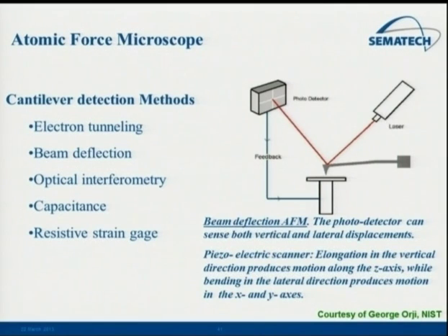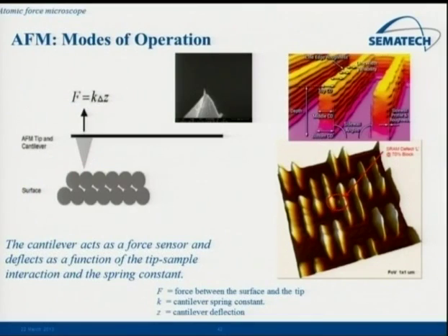The technique is fairly simple. You're dragging this cantilever across the surface, measuring its deflection, usually by an optical technique, to pull out effectively what the surface profile is in the vertical direction. So this can be an incredibly powerful technique to measure atomic layer roughness or, in some cases, the critical dimensions of features and start to extract a lot of that same profile information out.